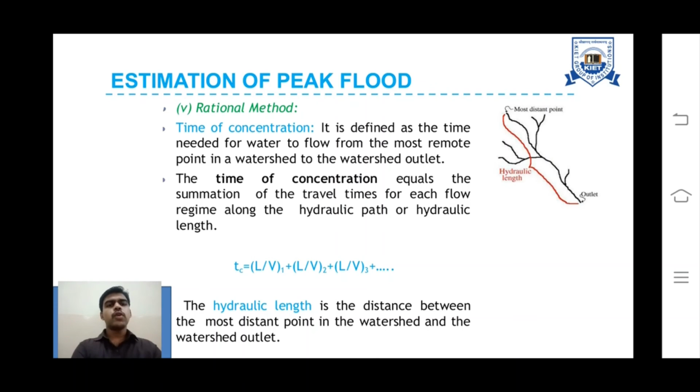Depending upon the time of concentration, the hydraulic length is determined. That is the distance between the most distant point in the watershed and the watershed outlet. So by considering inlet as well as the outlet, depending upon the time of concentration, how much time is needed for the water to flow from the most remote point in the watershed, we are considering the time of concentration as well as the hydraulic length, the distance between the most distant point in the watershed and the watershed outlet, for this estimation of the peak flood.